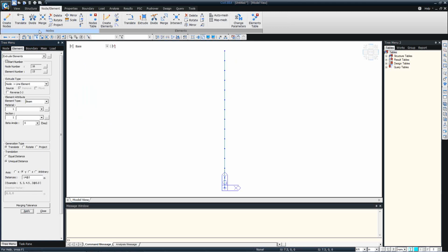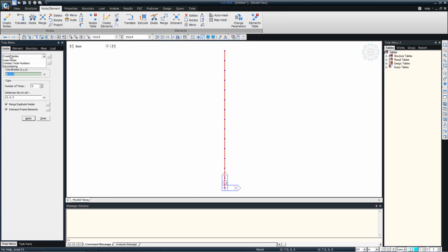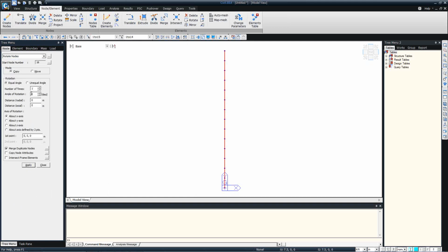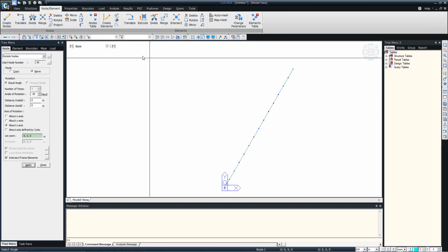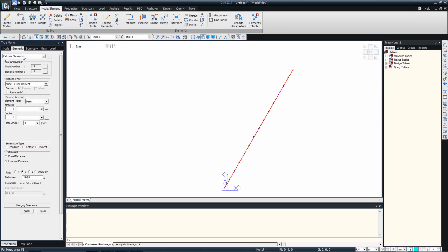And we'll create the skew. So orthogonal grillage involves when you have the skew angle greater than 20 degrees. So let's make it -30. Move. Oops, it's in the X direction, Z axis. Select everything, extrude elements in the X direction.